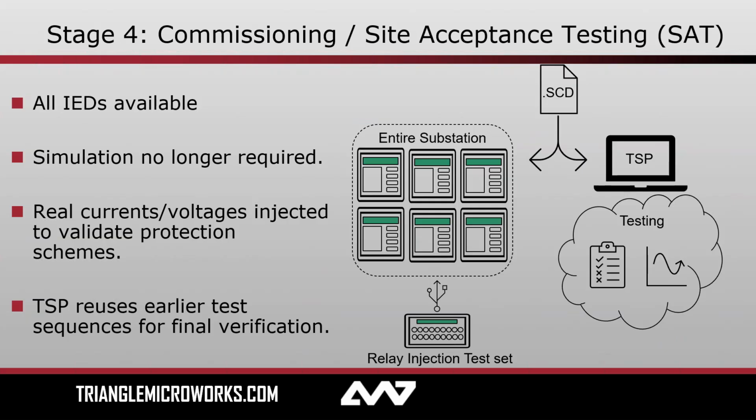And then we also have Test Suite Pro present here. So again, the same tests that I configured at the beginning that I ran against my simulation can now be run against those same IEDs. They're just now physical instead of simulated. Validate my signal exchange, make sure that my devices are all functioning correctly, and that the large protection, automation, control functionality that I've designed is actually working correctly. And if it's not, I can test and troubleshoot, visualize those communications, see where the breakdown is occurring.